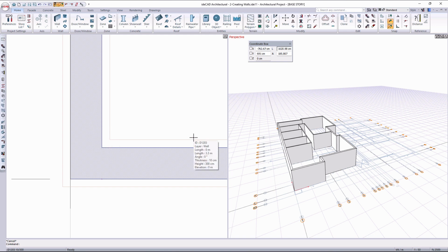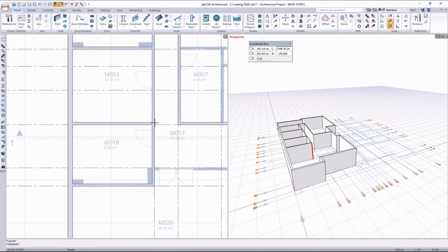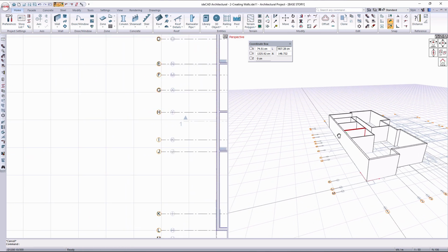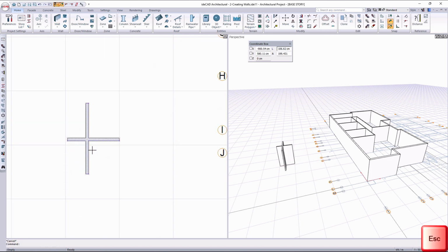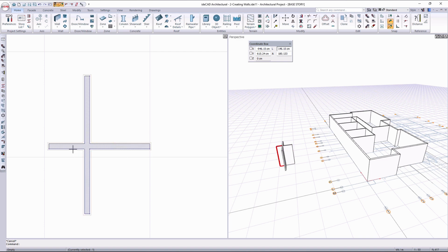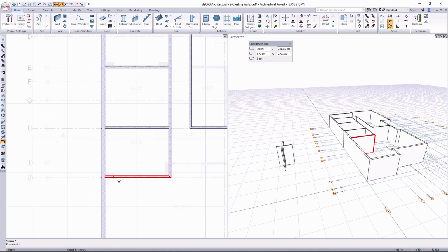If the plaster appears continuous across connected walls, it indicates that the walls are properly joined. In ideCAD, the first drawn wall remains fixed, while the second wall gets segmented where they intersect. Our recommendation is to draw the walls first, and then use the Trim Extend Wall command to split walls where needed. After activating the command, simply select the wall to be divided and the wall that will divide it. The order of selection does not matter. This makes it easier to make adjustments later, especially when placing zones, doors, and windows.